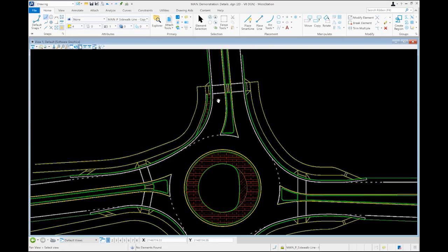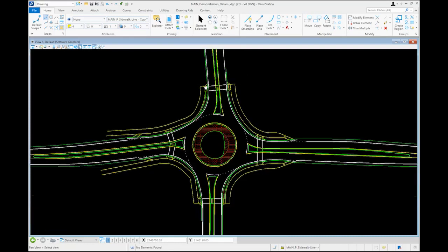And that was really just to allow for those crosswalks to be set so that the pedestrian crossings weren't cutting through those outside aprons. Along this east-west roadway, both of these were set back 1 car length, the standard location, because those outside aprons were not required in those locations.